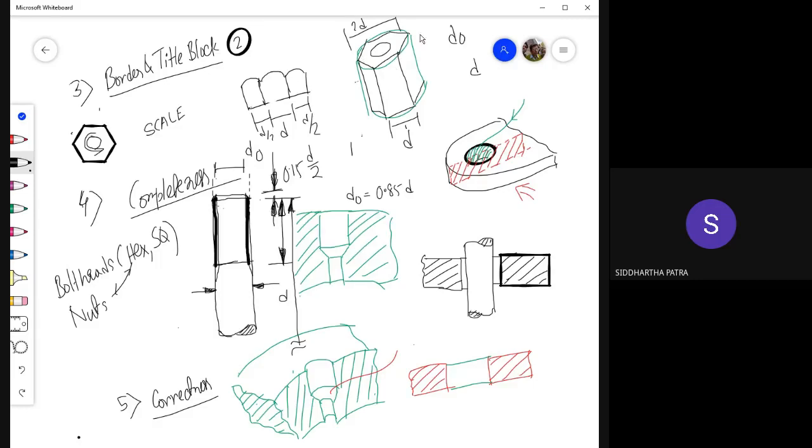So basically you take a tool and keep it at an angle and simply put it near the corners. You would be rotating this, going to be a bolt component, going to be a nut component, and then you put a file, let's say, this is a file that you'd be using to chamfer the geometry.